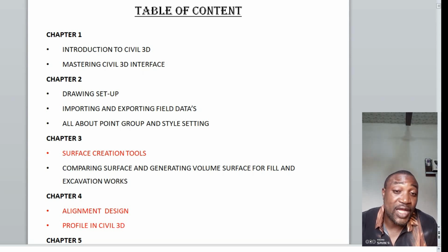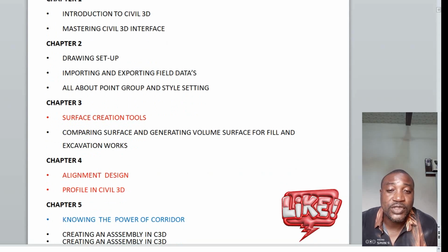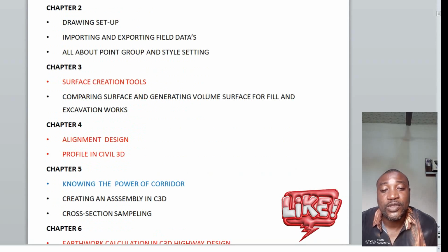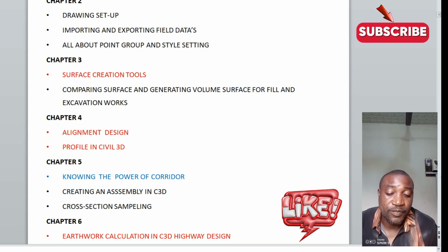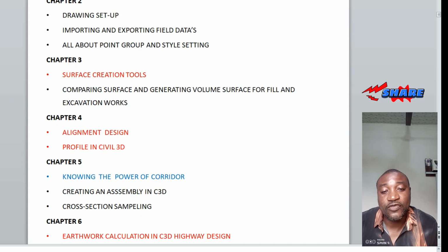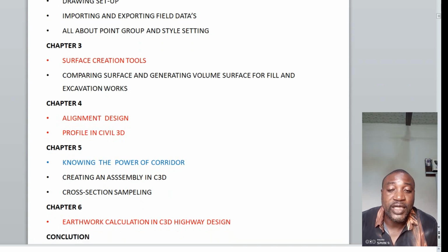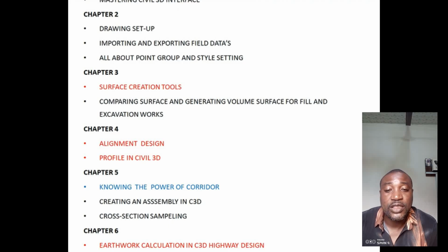to enable you to set up a style for your points, how you view them in Civil 3D, be it a full detail report on a particular road, maybe a road that contains buildings and trees. You should be showing the same items, the trees, in representing it in your point report style. So whoever accesses your information should be able to read it properly and easily. And where there are culverts, it will show the existing culvert there by the point style group.